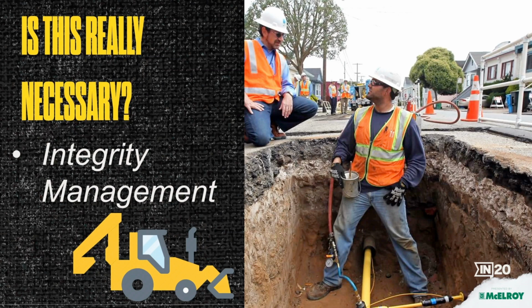One other method that I know is happening in some areas is a rolling physical inspection of the piping system. In other words, we're digging up sections of perfectly operational pipeline to physically inspect fusion joints and other components in that system. That sounds expensive, right? Yeah, and it probably is. In this instance, a properly performed documented pressure test could save the utility a lot of time and money in trying to meet that federal requirement, not to mention provide an easier way to ensure continued safe operation of the pipeline. And yet again, the pressure test is carrying a lot of weight.